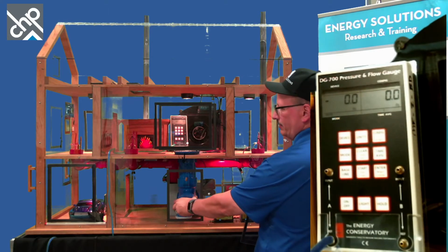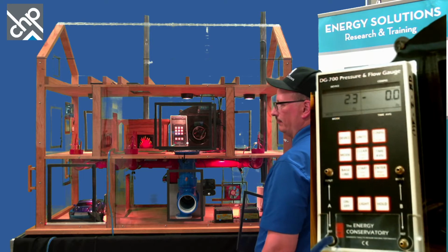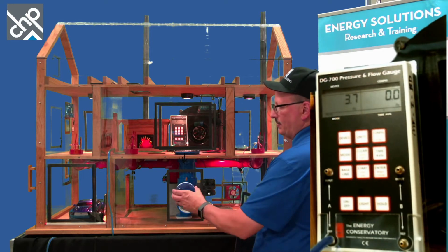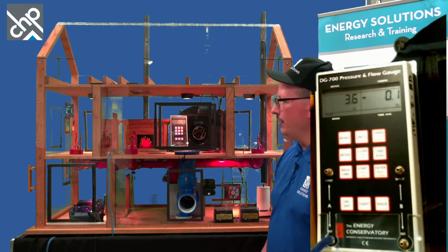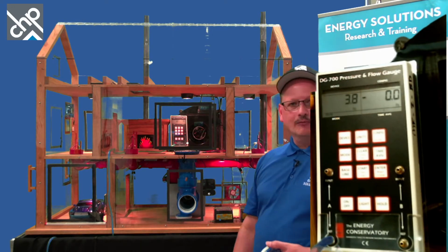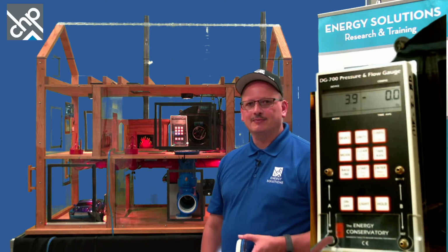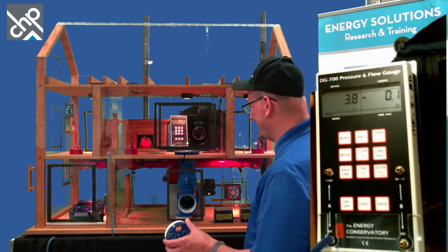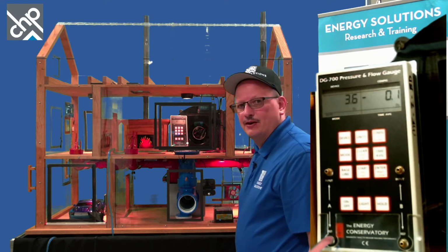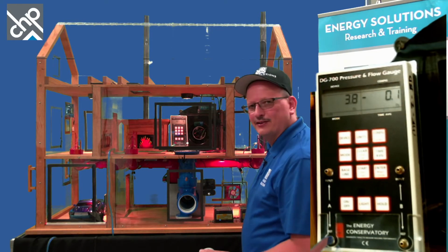You can see the manometer. When I open that leak, I opened a really big leak. What happened to the pressure in the building? It went positive because now we're blowing more air into the house than we're pulling out. And if you notice, the fireplace, is it working now? It's working really good. The smoke is just flying out the chimney. So it's burning a lot of wood real fast, but you maybe wouldn't have the fireplace and the furnace on at the same time, but you could.